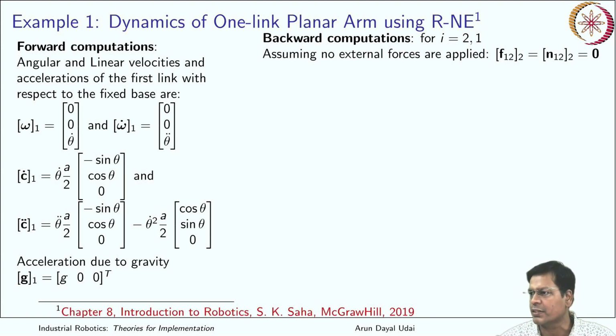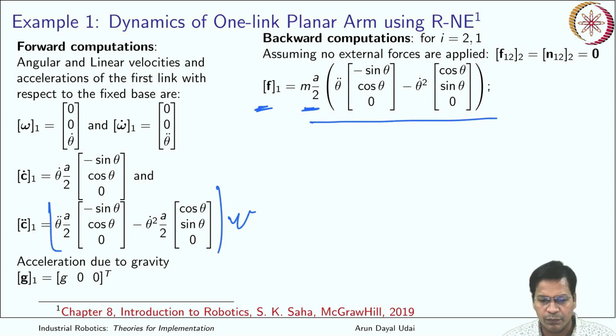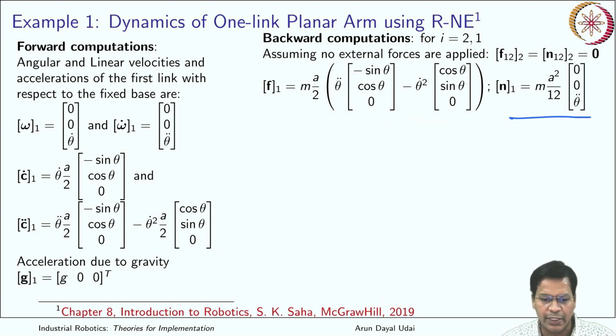Because this link is a terminating link, there is no link that comes after this. So this makes the force and moment equal to 0, the ones that come from the link which comes after this. So that is equated to 0. Now force is simply mass into the acceleration which is there. So the acceleration, you know, it is exactly this one. So this goes inside, that comes here. So that is the force. Okay, and the moment is again I theta double dot. Okay, so I have simply used this to obtain this.